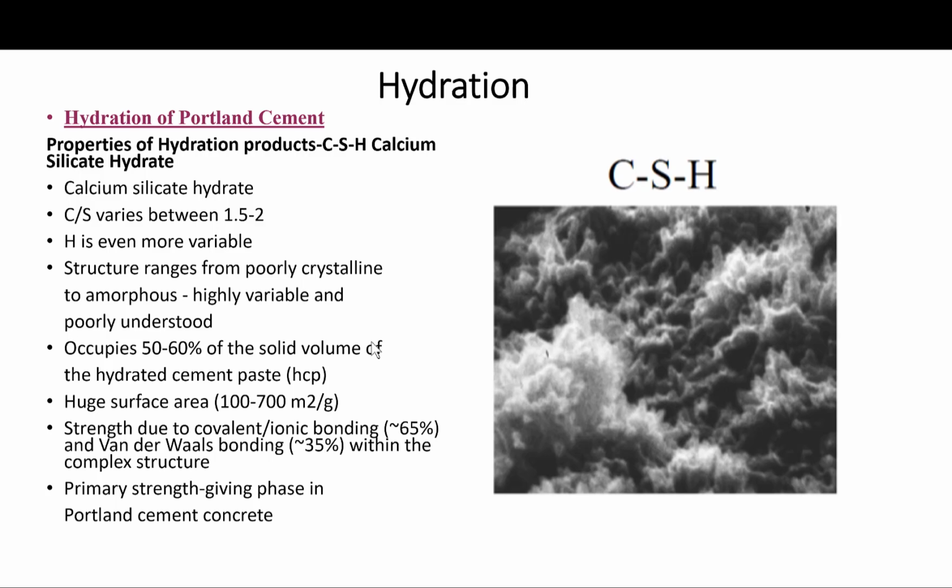The strength of the material is attributed mainly to the van der Waals forces, and I have mentioned that before. Also, the size of the gel pores, or the solid to solid distance, is reported to be about 18 angstrom.